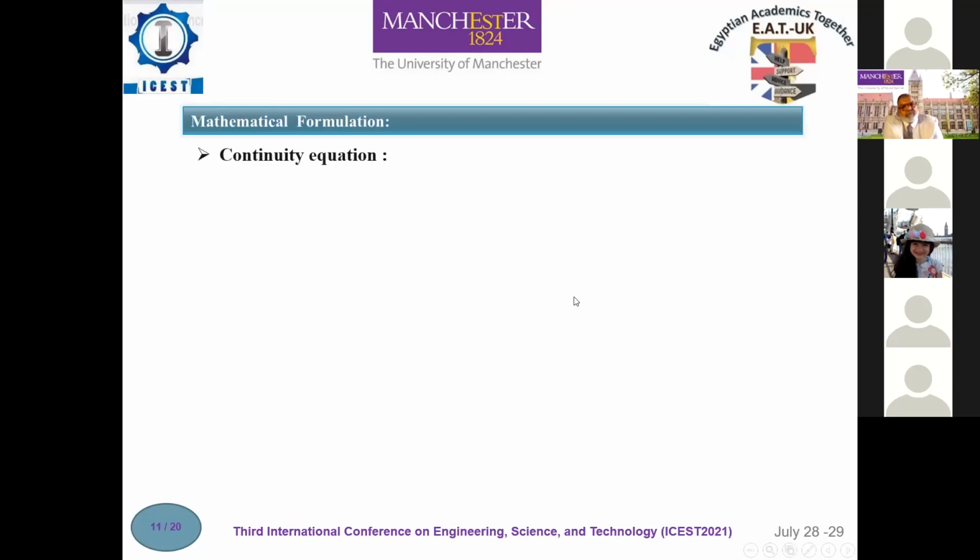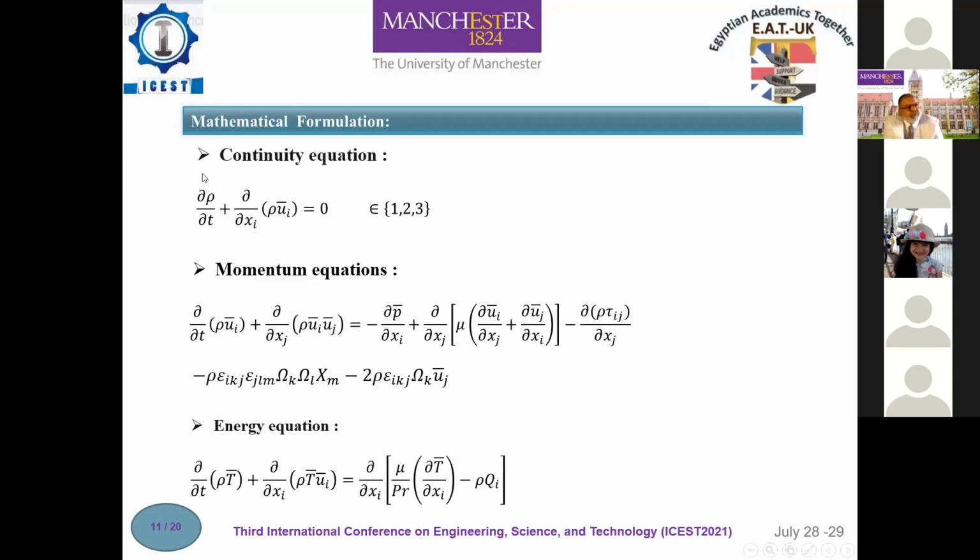The large eddy simulation equations in tensor notation for a three-dimensional, time-dependent, and incompressible fluid are expressed as follows: continuity equation, momentum equations, and energy equation. The STAR-CCM+ CFD code is used to run the simulation using the WALE subgrid scale model to capture the small eddies of the turbulent flow, and of course with the use of the finite volume approach.